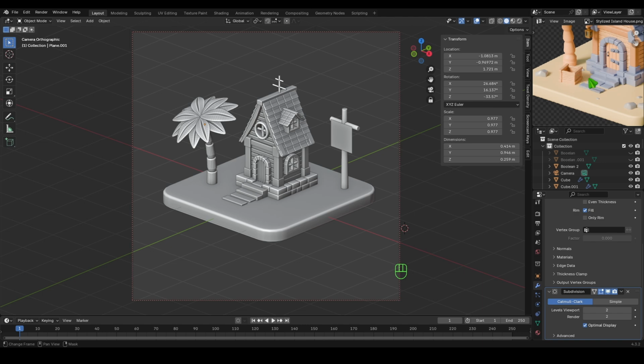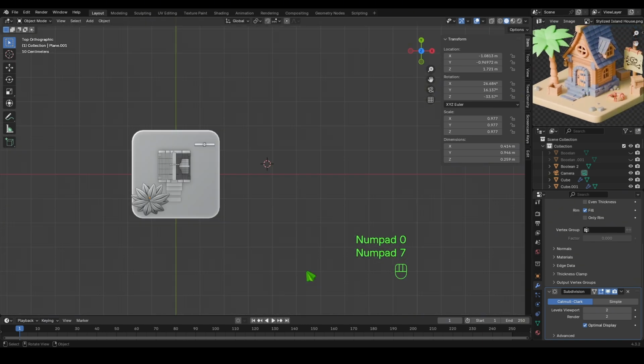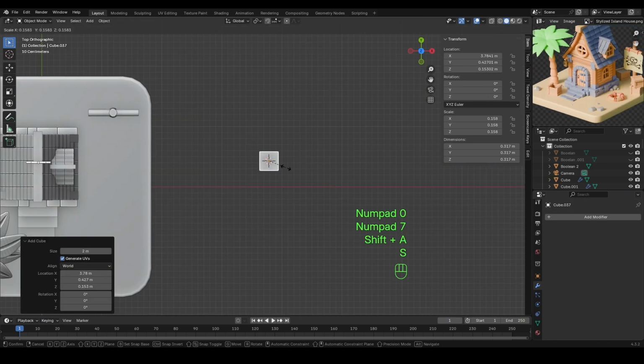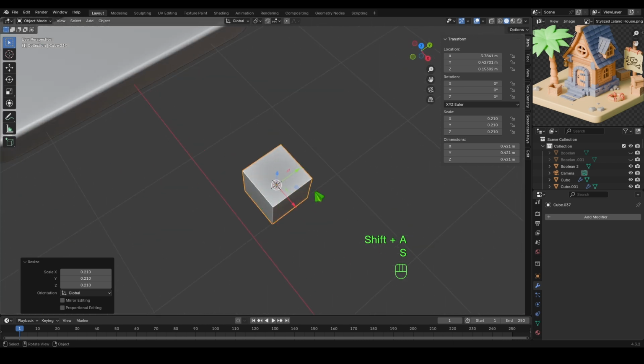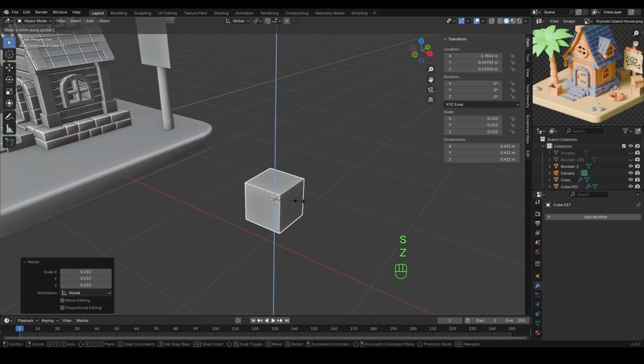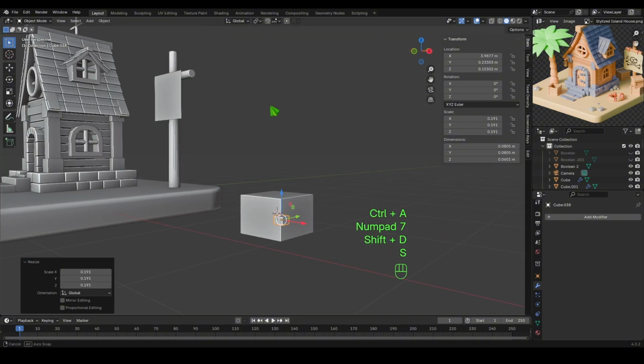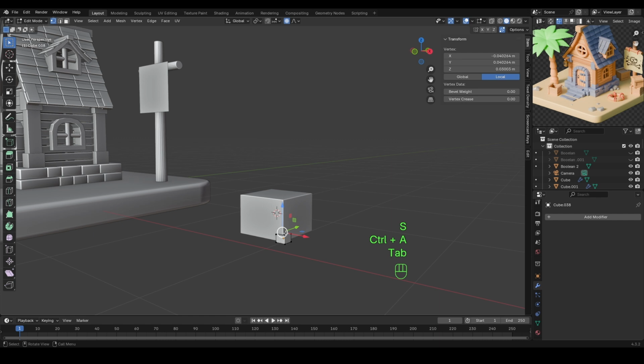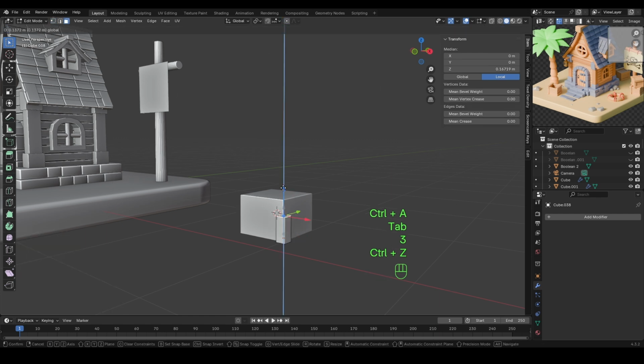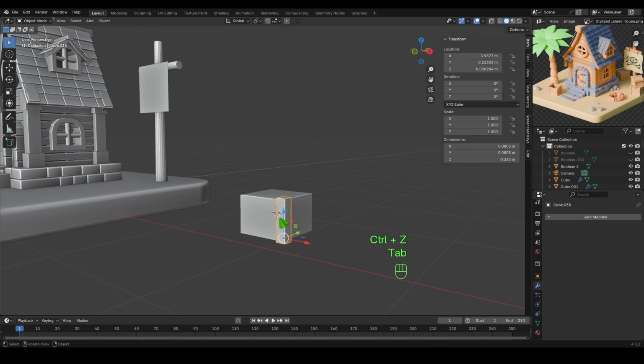Let's make these boxes. Okay. We need a cube, mesh cube. Let's scale it something like this. And now, let's scale it a bit down. And Shift D to duplicate. Let's scale it to the side, move it down. Let's scale, go to edit mode. And turn off the proportional editing mode and move it up. And let's apply the Mirror modifier.